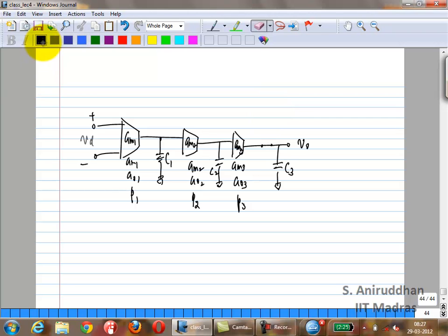Okay, so let us say you actually start off with none of these guys, right? You have designed each stage separately. Now you want to add the compensation capacitance. First of all, what's going to happen? We first need to compensate the inner loop. So what we'll do is we'll add C prime.